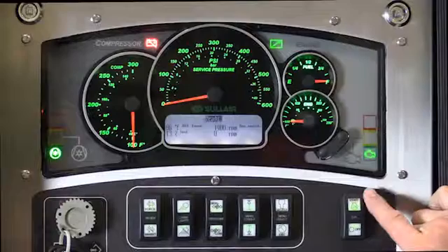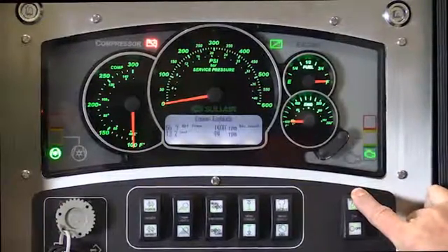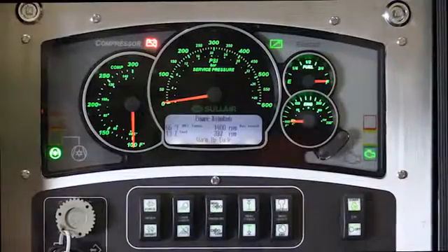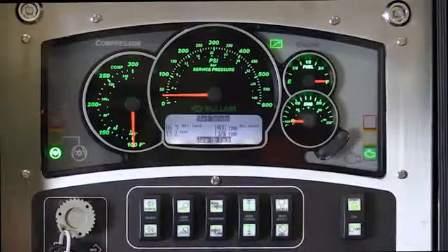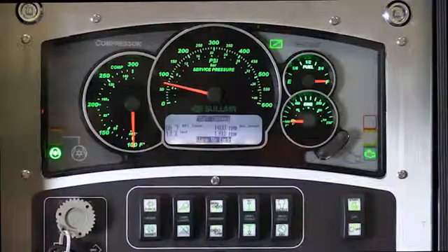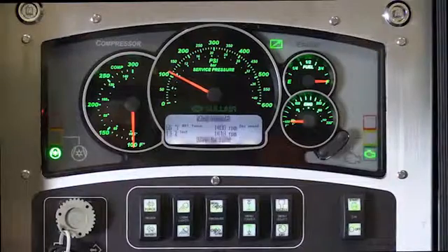We will now demonstrate the startup of the compressor. For a manual start and from the ready state, toggle the ignition switch to the start, in other words crank position. Once the switch has been pressed to the start position, the controller will check status and automatically continue to energize the starter until either the engine starts or the maximum crank duration has been reached.